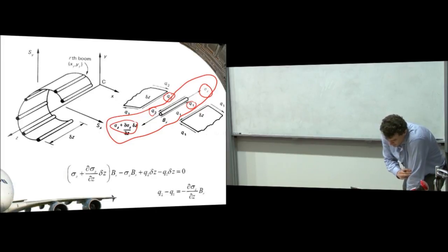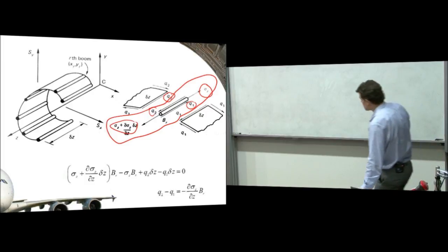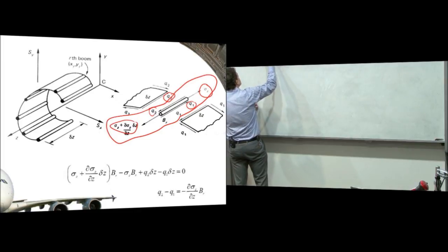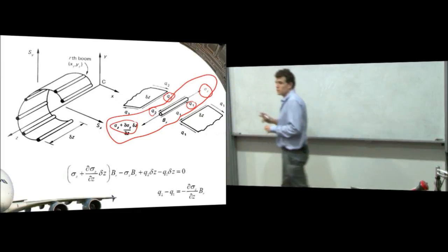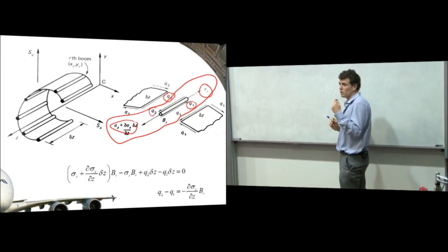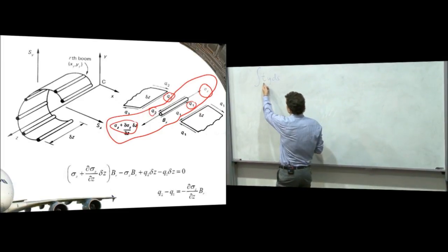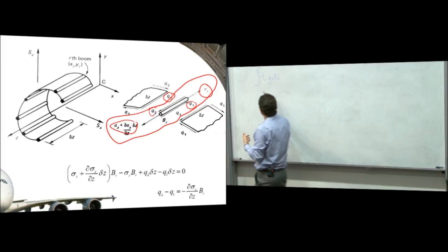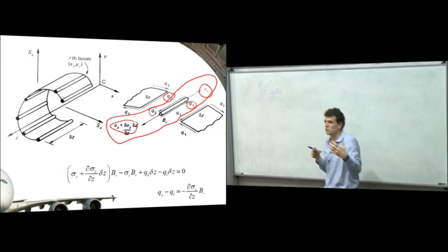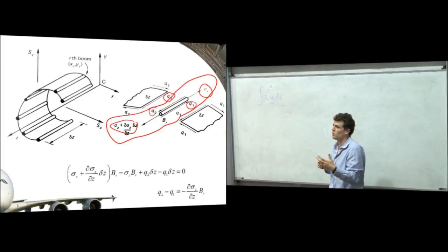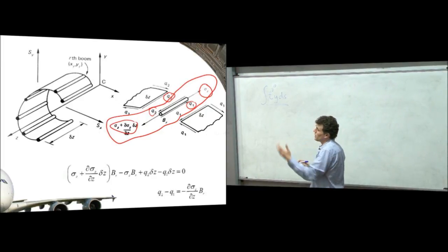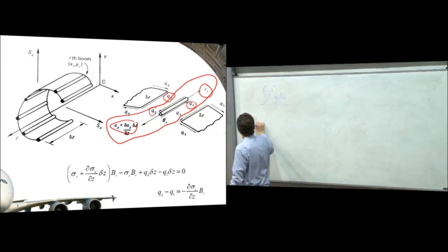Now the benefit of this technique, remember last week in our calculations we had this integral ty ds in our calculations. Now because we've assumed the thickness of the panels is 0, there's no change in this. If t goes to 0, wherever t is 0, there's no change in that integral. The only place the shear flow changes is when we cross over from a boom into the next panel. So for any panel, the shear stress is constant, or the shear flow is constant.